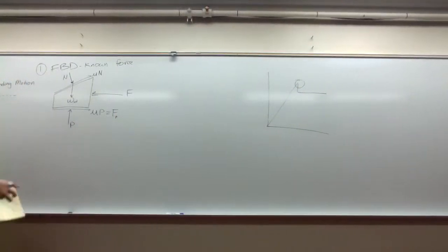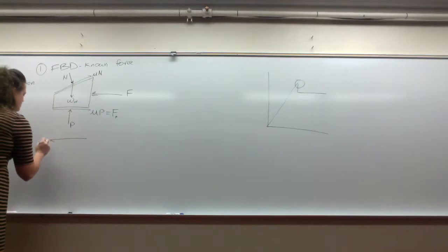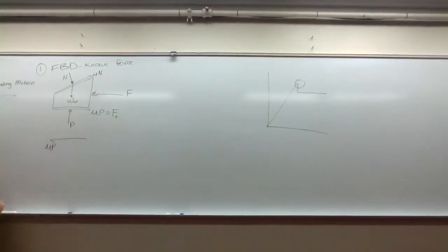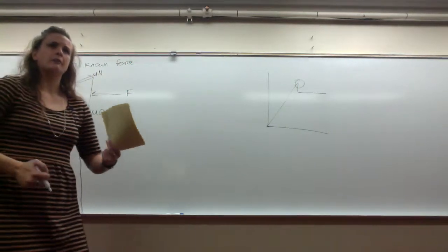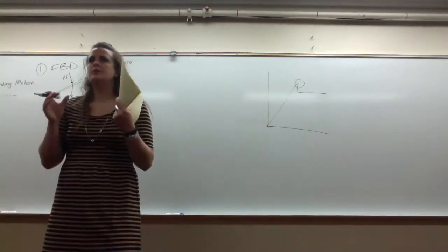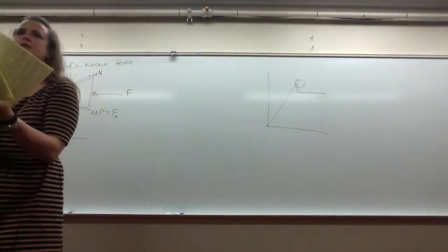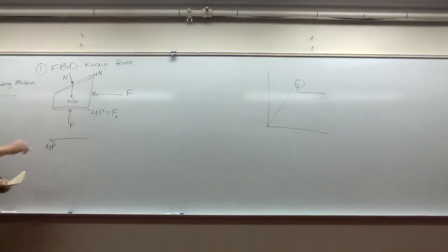Because if we draw our friction force to the right, what is that actually doing in the system? It's assisting the motion, right? We're getting help from friction, and that doesn't make any sense. So this is your green light, when you see these wedge problems, to use your intuition, because you have to overcome the friction in your direction of impending motion.